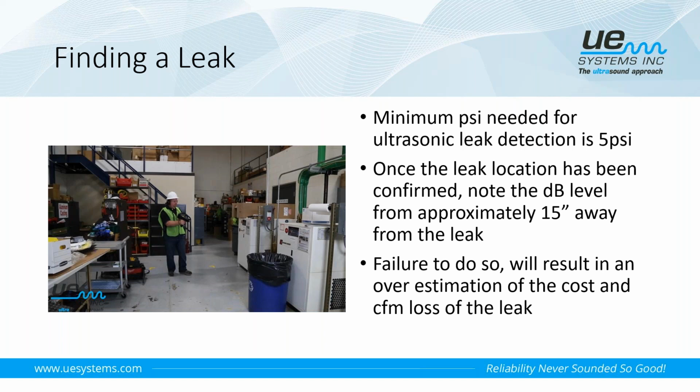away from the leak. So once we've identified exactly where that leak is coming from, we just simply back away approximately 15 inches from the end of the rubber focusing probe, and we'll note the decibel level reading from that distance. If you take those decibel level readings too close to the leak, it tends to overestimate how much that leak is costing. So in this short little video here, there won't be any sound with this video, but you're going to see that's exactly what we're doing.